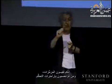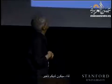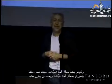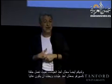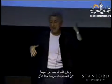So you're sensing, you're measuring the encoders, and then you are going to compute your controller, and then you are sending this controller to the motor, and the motor has some time constant, so you have some delays. And you have also the sampling rate. The servo loop is running with some sampling rate that needs to be quite high. And this is not anymore a problem. It used to be a problem when we had slower computers, but now the CPUs are so fast that this is not anymore an issue.